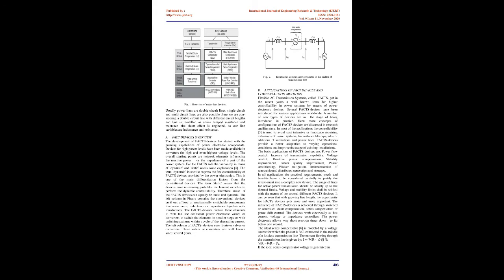By using TSSC, Thyristor switched series capacitor, we are actually offsetting the line's inductive reactance, thereby reducing overall line impedance. The variation in line parameters is a function of conductor length. The line parameters are resistance, inductance, and capacitance. These variables have fixed values rated as resistance, inductance, capacitance per unit length for a particular conductor.